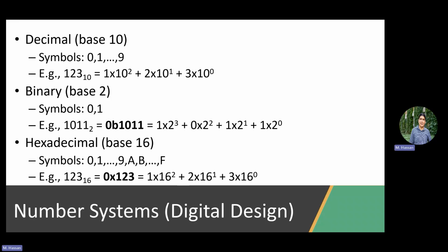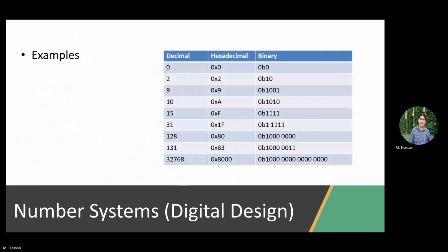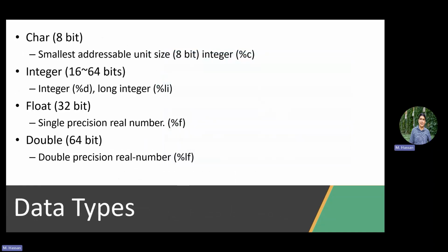Some of the things we said, I need low-level hardware control, which means I need to access certain bits and certain registers. So you need to review really how we handle things. As an embedded systems engineer, you need to be aware of numbering systems, which are mainly in binary. You need to access particular bits. We use a feature called bitwise manipulation a lot in embedded, to control certain bits in a register through masking. So these are a few slides I only have there so that you have them when you study. You just refresh your mind about numbering systems, data types, and all that stuff.